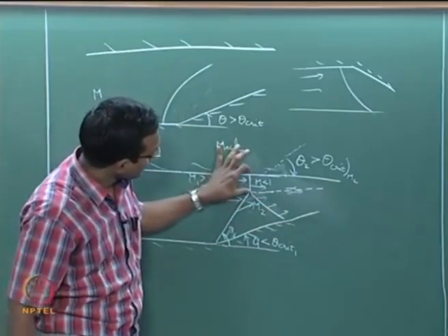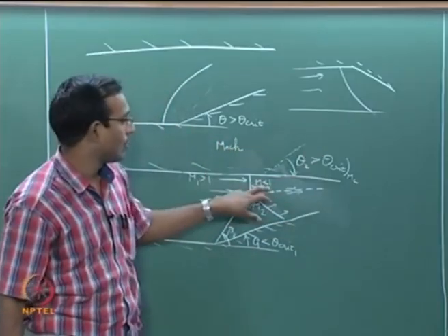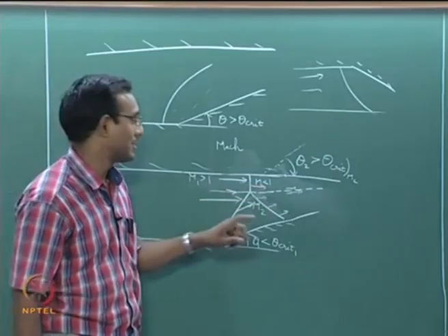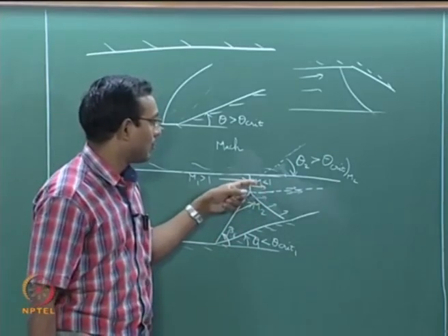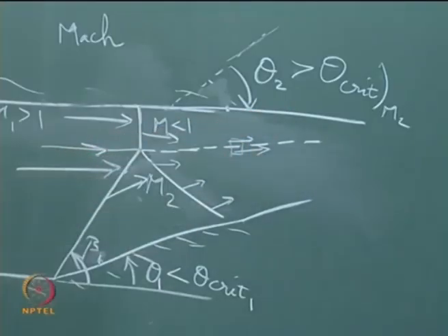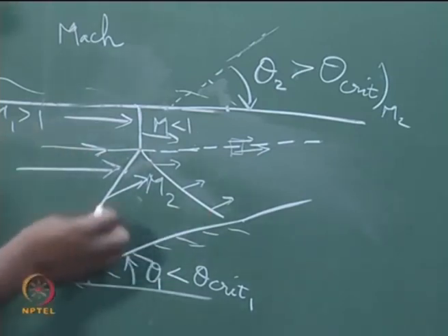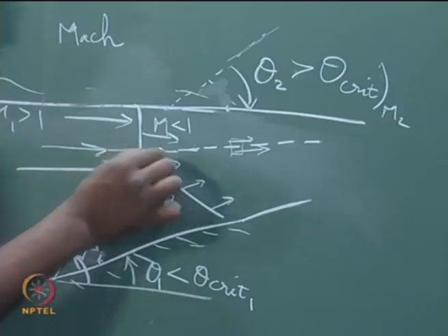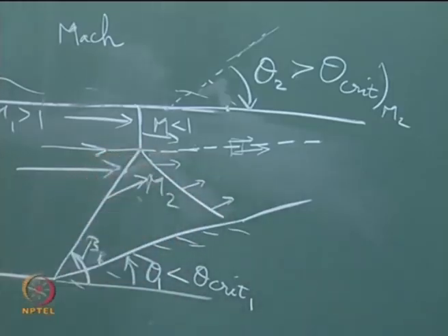Now, you are seeing a convergent duct for subsonic flow. What should happen? Flow should accelerate. So, the flow here is going to accelerate. What about the other section? Here there is possibly a region, I am not sure about what will happen in this zone, probably there is some subsonic region, but mostly it is all supersonic region.